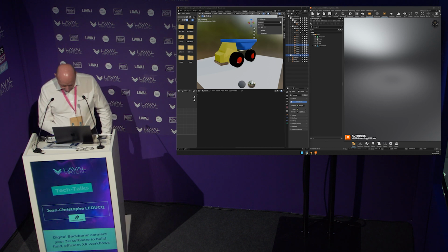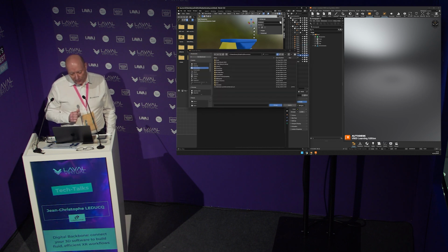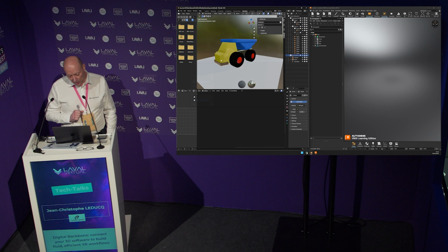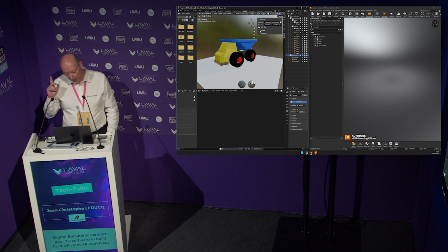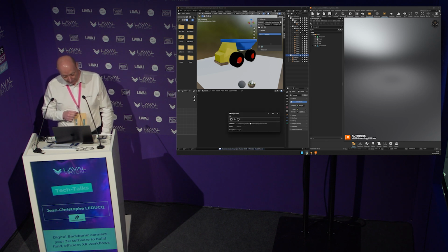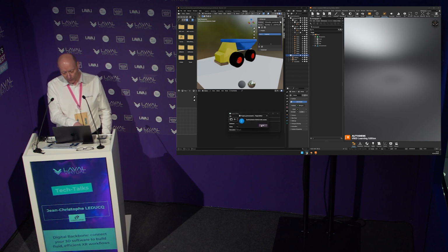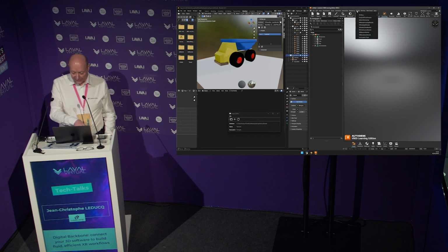So what it gives, I have a short video. On the left you have Blender, on the right you have VRED, and we have the small connector in each software as a plugin. If I run the video, you have the toy truck, a very simple model, just for the demonstration. In Blender, we connect to the digital backbone and we say, I want to save that project in the digital backbone. Then, by clicking that button, we project the Blender dataset to a VRED dataset.